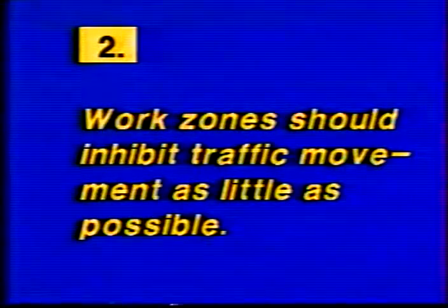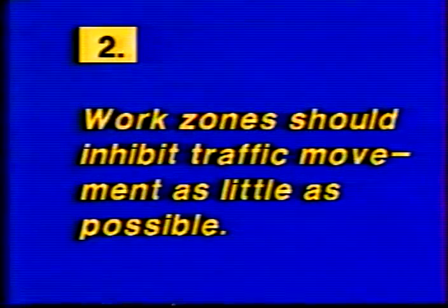The second principle is that work zones should inhibit traffic movement as little as possible. To some drivers, a work zone can seem like an obstacle course. They may be confused by the changes in road alignment and distracted by the workers and equipment. The closer we can keep the work zone to normal driving conditions, the better for everyone.